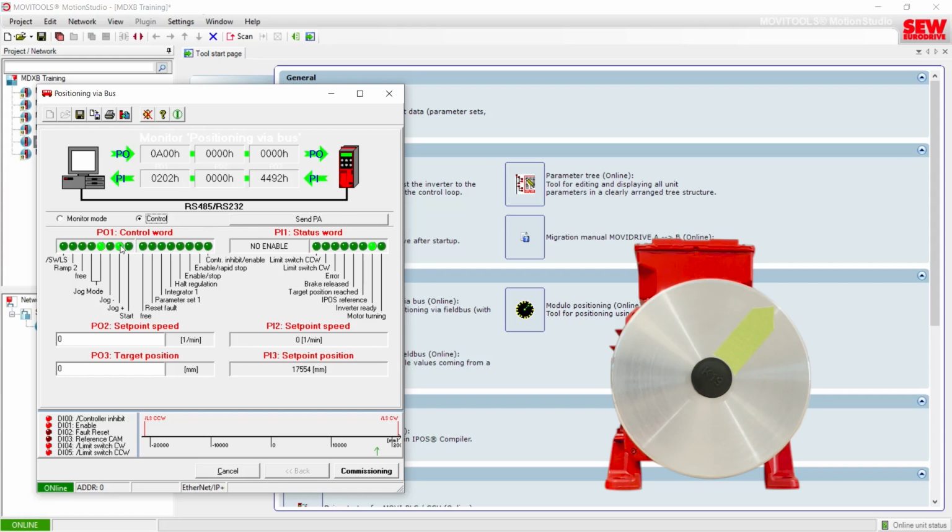Okay, so the next thing I need to point out is the mode bits. If you remember from Lab 9 Part 2, over on the right-hand side of the screen, there is a key telling us what the mode bits were and then how we can get into different modes using 2 digital inputs. We don't have a key for this application module screen shown right here in the top, but it is over here underneath these 2 bits, and then it currently shows reserved. If you hover your mouse over this, it will give you a pop-up telling you the different bit assignments to get into the different modes.